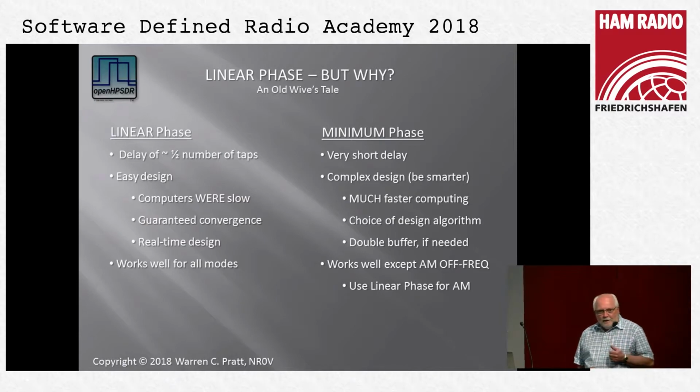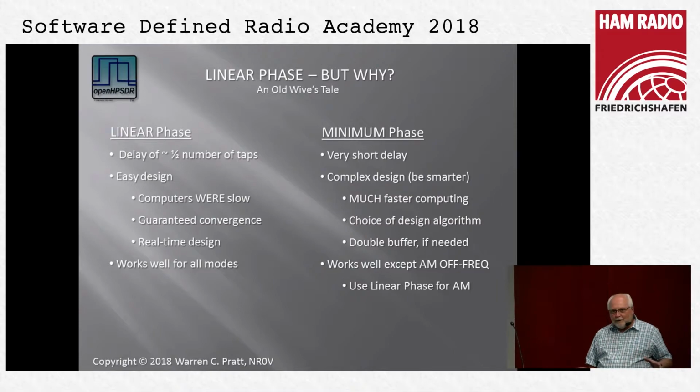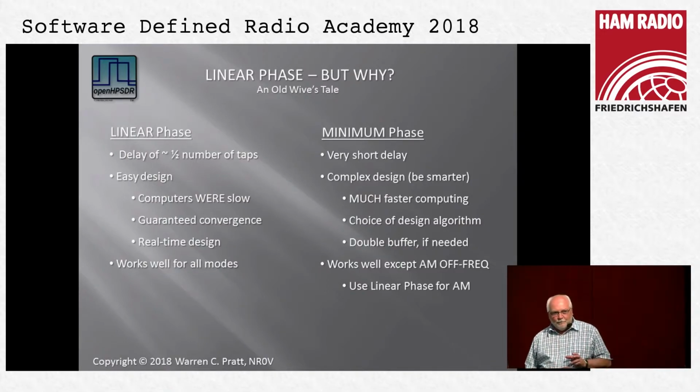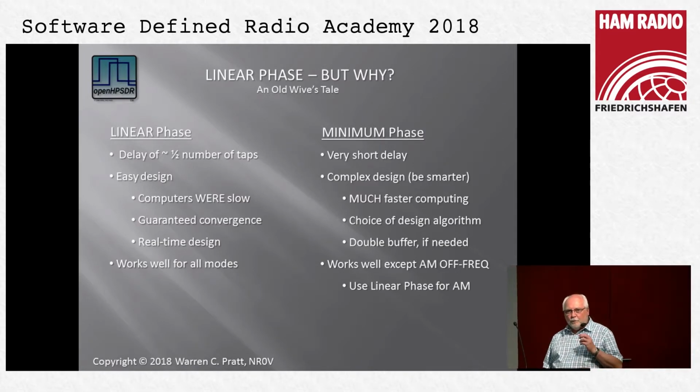Now, let's go back and examine linear phase. There seems to be this belief that linear phase is required, for example, for our bandpass filters. It's absolutely not true. There's another class of filters called minimum phase filters, which have a much lower latency. Perhaps the reason that linear phase filters became so popular is because they're easy to design. There's easy algorithms, guaranteed to converge, don't require much computing performance.